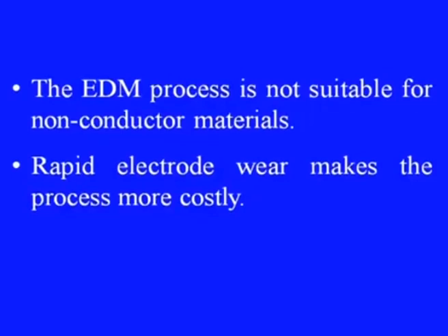Then let us look at the limitations of this process as well. Material removal rates are basically low, making the process economical only for a few hard and difficult to machine materials, not for all materials, as we have discussed already. Recast layers and micro cracks are inherent features of this process, and this makes the surface quality of the machined surface poor. The EDM process is not suitable for non-conducting materials.